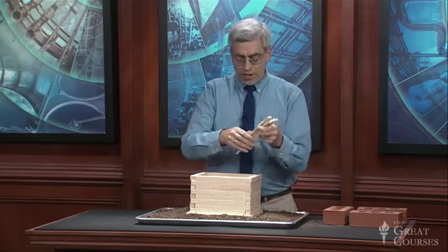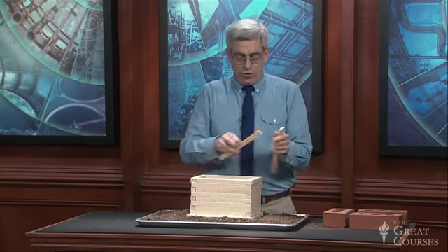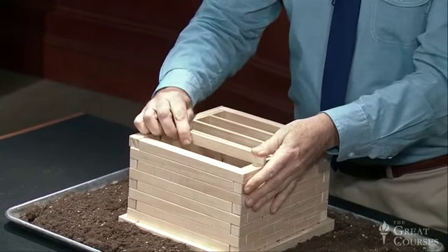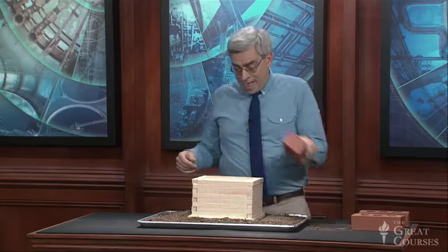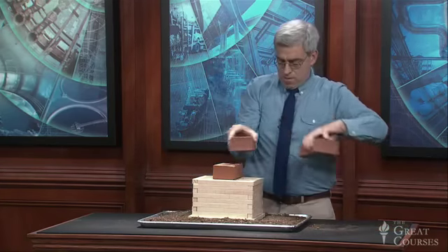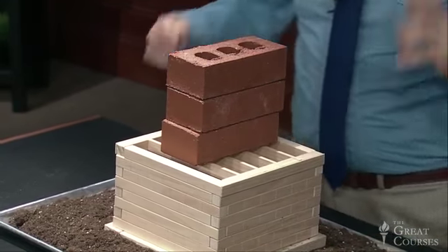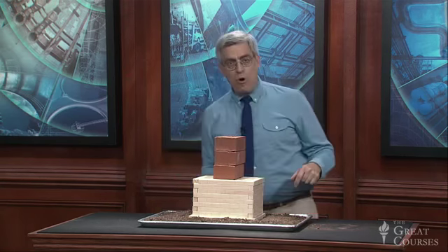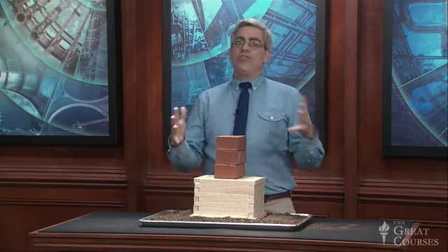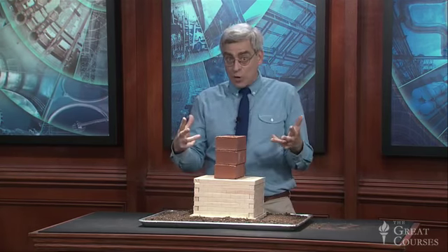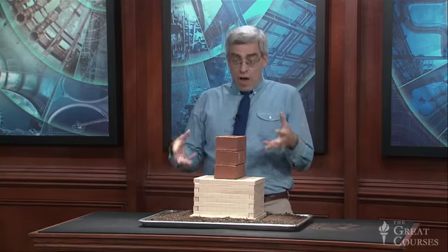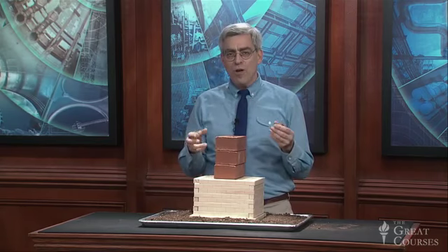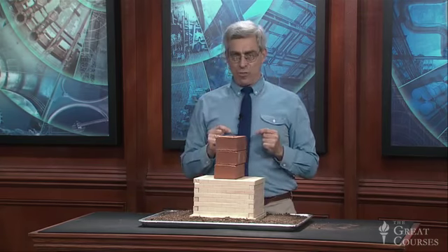Once again, I'm going to replace those joists set into notches in the two side walls. And now we can add that same gravity load. But at this point, I can add substantial lateral load, not just in this direction, but in the perpendicular directions as well. And this structural system is now capable of resisting wind loads and gravity loads of significant magnitude. So clearly the rigid walls of a bearing wall structure provide inherent lateral stability.